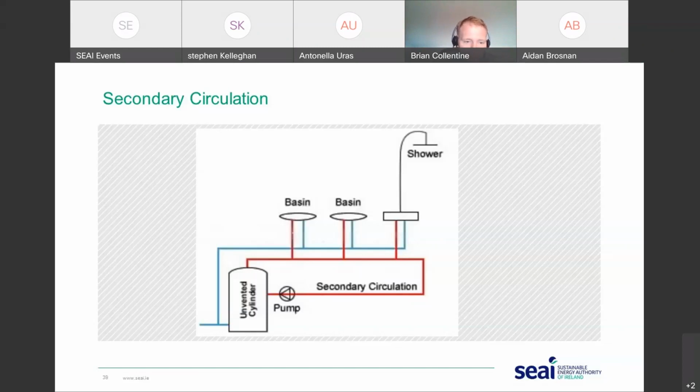Very identifiable on site. You would see it in the plant room generally. A hot water return pump generally is on the return side, and generally they're labeled anyway. You'd also see it in the bathroom itself. You might see it under the sink, where you can see the hot water tap coming to the sink, and generally about 300 mil away from that there'll be a return identifiable. So it's easily identifiable on site if you look for it.